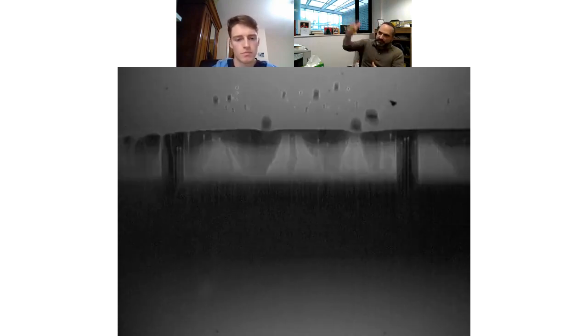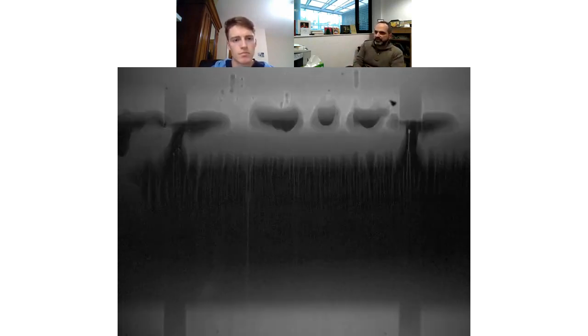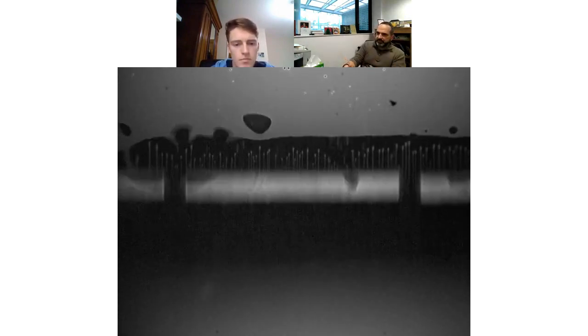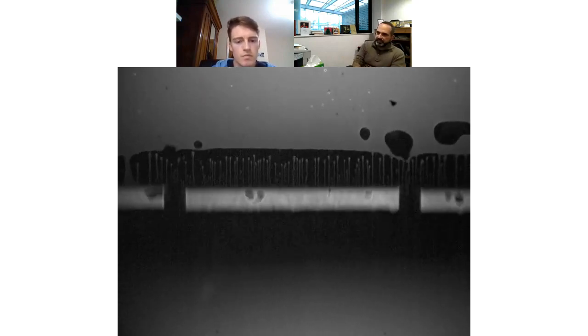So this is what happens. If you slide up and down, because this is a fluorescence experiment, the areas which are brighter are where there is more fluid. The areas which are darker are where there isn't very much. And you can also see this very nice formation of bubbles. You can actually see this cavitation happening and also see the interaction between the texture and the film forming.